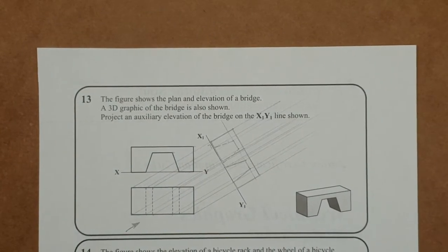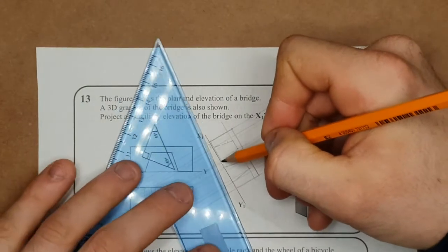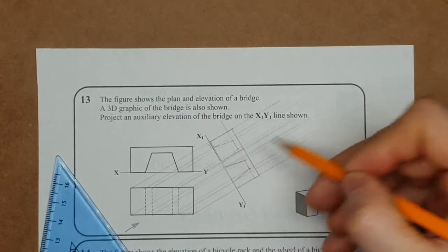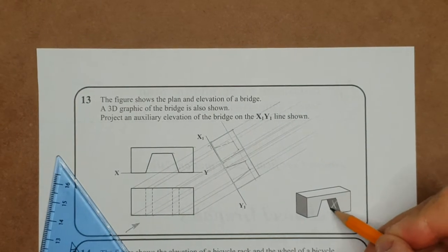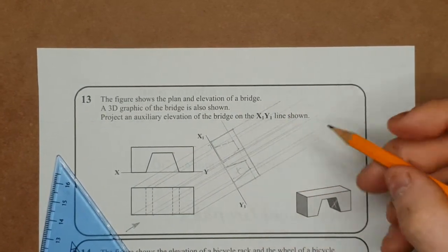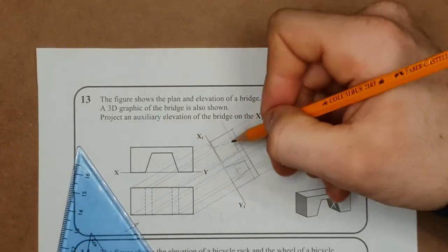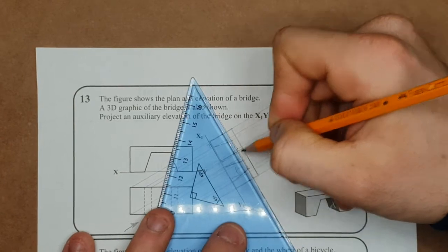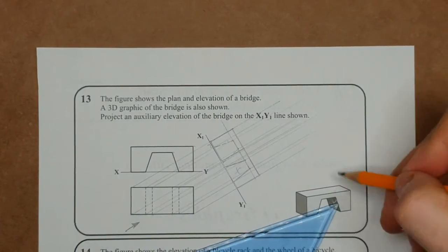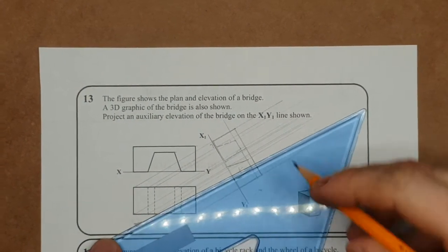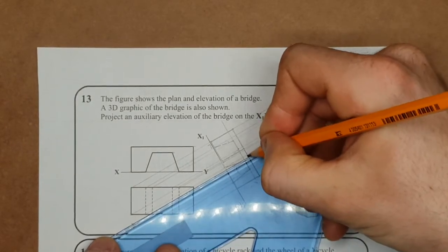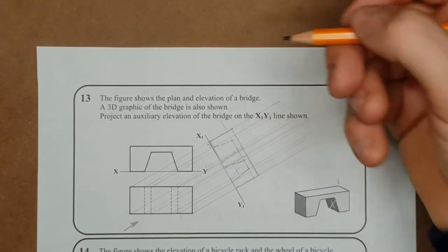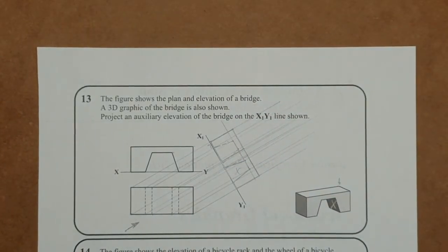Any detail that's missing here now? A very common one that might be missed is that the baseline of this actually has to be fully solid all the way through because of this inside surface here that I've just put an X on. That's it right there. Second last detail that a lot of people would miss on this would be a little bit of hidden detail along the top edge. And the very last detail is this back edge down here. Dropping that in as hidden. There's a lot of detail on such a small little object.